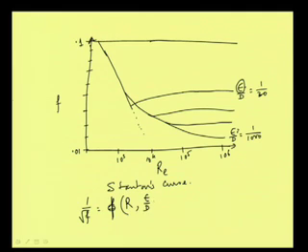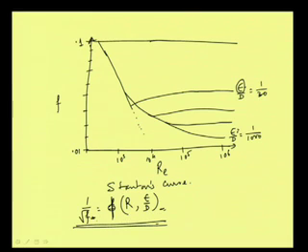As a function of all those, some logarithmic relation can be developed, and different investigators have given different expressions from their experiments. Colebrook gave one equation, and in the Jain book we get another equation. So, such expressions are there, and we can use these equations also for calculating the f value using the Reynolds number and this roughness ratio, roughness by diameter.